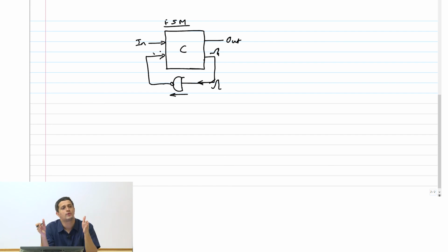I can define how much delay I want, and make my system work at different clock frequencies. Here, there is only one clock frequency at which the system can work, where you make sure that delay matches over all process corners and all that, then the system will still work reasonably. But there is only one delay and one clock frequency at which it can work, right? Of course, you have to give enough delay. You can't give like 30 picoseconds and expect things to work, right? You have to give enough delay so that you can do something with it.